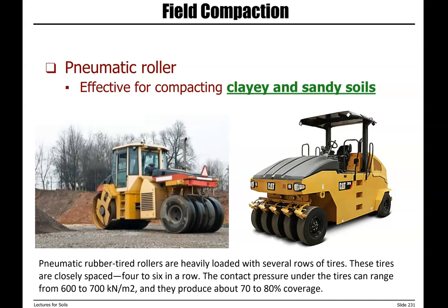Pneumatic roller: these are suitable when we have clayey and sandy soil. So these are pneumatic rubber tired rollers, and in many cases these are more efficient compared to a smooth wheel roller. The load is applied using several rows of tires, and these tires are, as you can see in the picture, closely spaced.